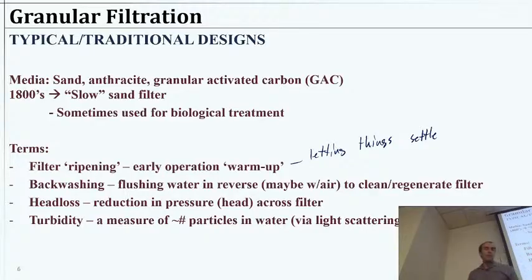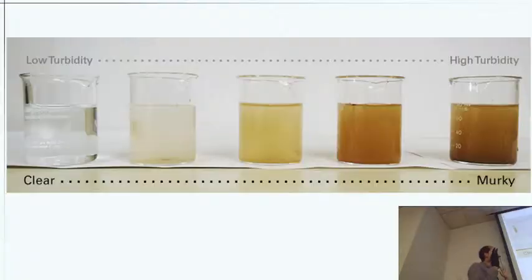There are other things that can happen if we get too much pressure, because now it's harder for water to pass through. You end up adding more water on top. That's putting more pressure. Eventually, if we have too much pressure, we'll kind of just part the sand and water will just flood through with no treatment and carrying all the dirty particles that they just moved around with them. So we could have a big spike in dirtiness, turbidity, and we know, hey, emergency, we should have stopped sooner. So there's a few ways we can trigger this, okay, it's time to backwash.